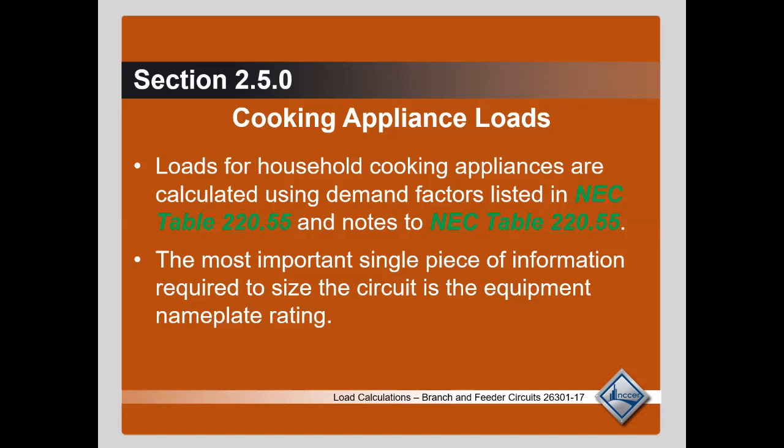Should have been on the very next page. Right there. Look all the way in the far right column. How many appliances? One. Yep, rated at 8,000 watts. Because it says, note the maximum demand is in kW. So say 8,000 watts. The single most important piece of information required to size the circuit equipment is